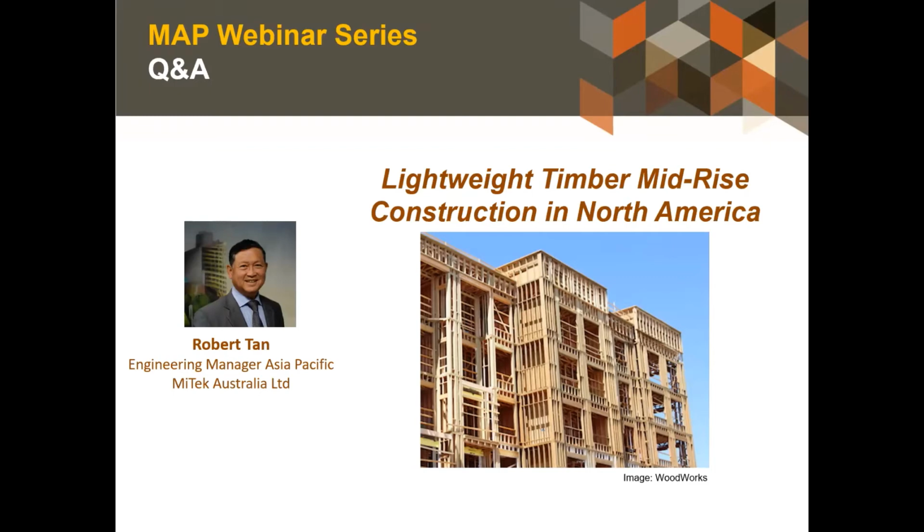The next question down from Gerald: I noticed a lack of noggings in walls that appeared to be approximately 3 meters high. Yes, you're right. That is one of the things that we did observe quite markedly. They do not use nogs extensively. Perhaps that's why they have 140 studs as much as they do over there as well. In the Australian rules, we do often rely on the nogging primarily for stabilizing the studs during the construction only.